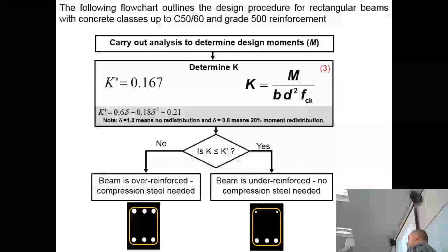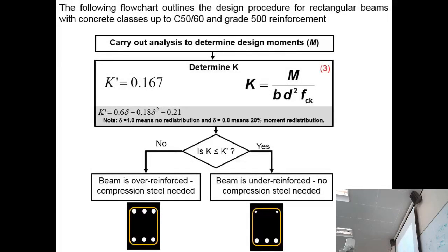Can I ask a question? You can ask a question. Mainly it's not about the calculation. What happens if you have too much steel in the concrete? It won't bind. If you have too much steel, you can end up with problems with the aggregate. Your steel has to be spaced correctly, so that when you put your aggregate in, it goes in between the bars. There are all different rules to make sure of that, but you can have too much steel in.